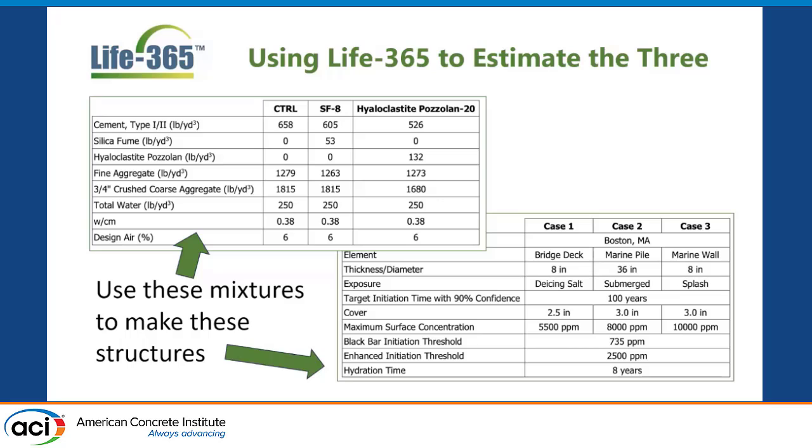Exposure conditions for de-icing salt, submerged, and splash. Life-365 has some presets, roughly speaking, for what those are, but I've already had to override some of the exposure conditions, and so I don't want to try to choose those presets. I want to go into something that looks closer to the actual numbers. And some of those numbers, like the maximum surface concentration, I can convert into percent weight of concrete and use those numbers. The cover is pretty straightforward. Life-365, I think, will go down to 2 inches. Below that, we start having a problem with numerical accuracy of the model because it's a slicing model.